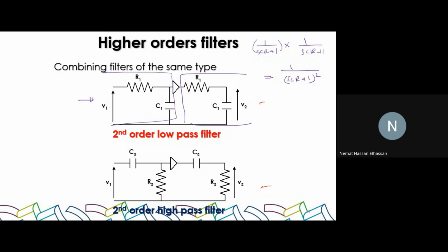Do we want that ideal characteristic? But for example, you're designing a consumer electronic, which we'll explain in a moment, the sound to light filter, which is your group project. You want to create something lightweight, portable that you can carry around. So if you increase the size of the filter with that method, the size of your device will increase, right? The battery life will decrease because you're using more energy. So it's a trade-off. As a designer engineer, you have to sit down and decide which way is the best that suits my requirement or my application. Okay? Is it more important to have the ideal characteristics? Is it more important to have the lower energy consumption and so on? Clear? It is always based on the application.